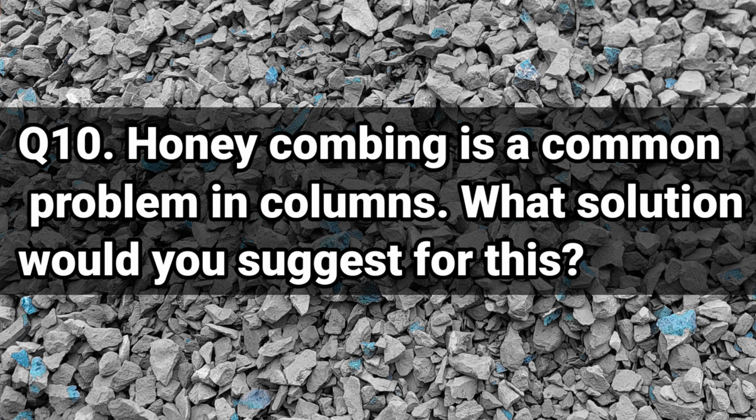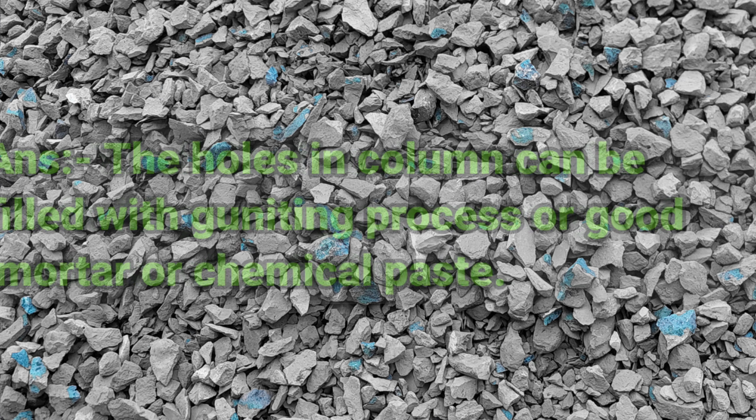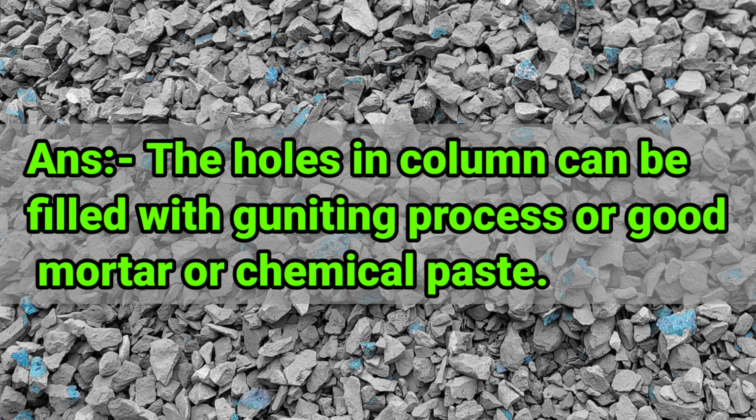Honeycombing is a common problem in columns. What solution would you suggest for this? The holes in column can be filled with grouting process or good mortar or chemical paste.